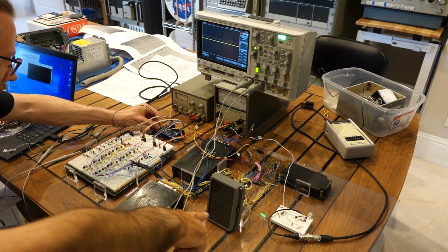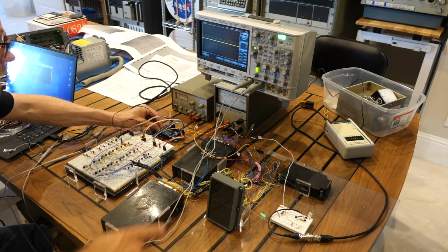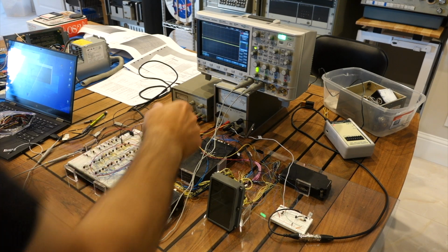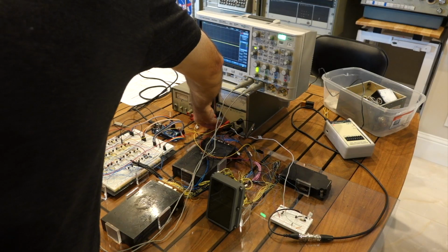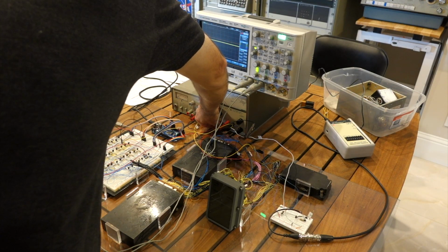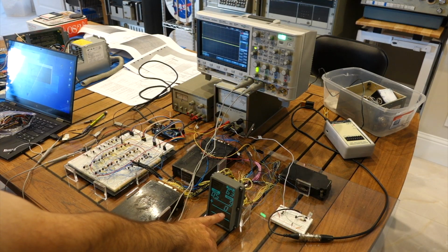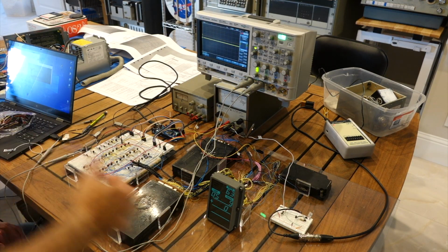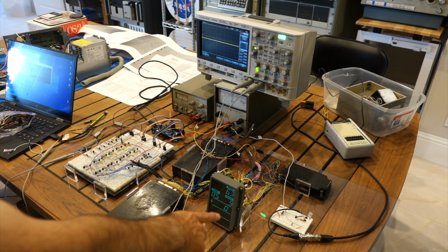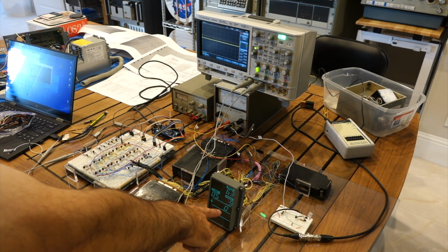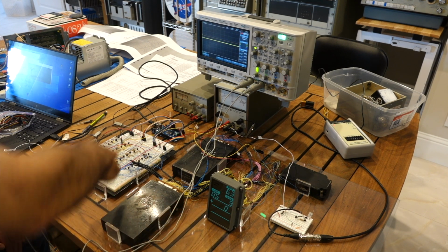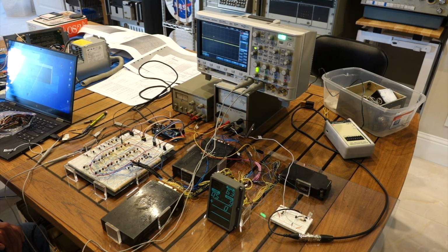We have the 0 in 1202 always stuck. Actually, if we turn it on for a second, we should see that it's always at 0. And right now I'm pulsing it on and off because it's not responding. So we have to figure out why the relays don't work, and we have to go through the relay drivers. And Eric jumped in. Your new recruit.